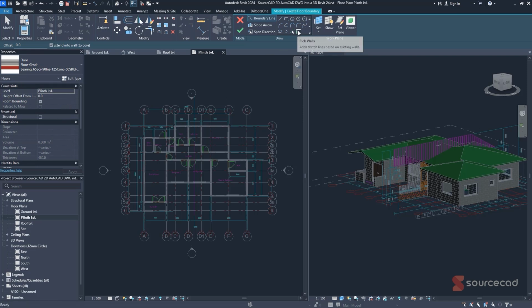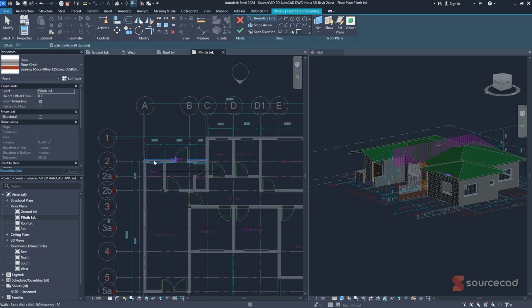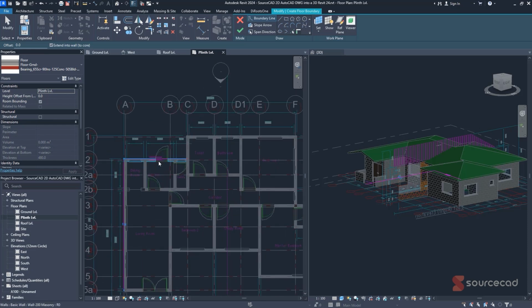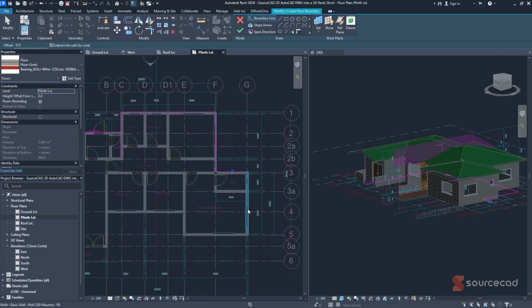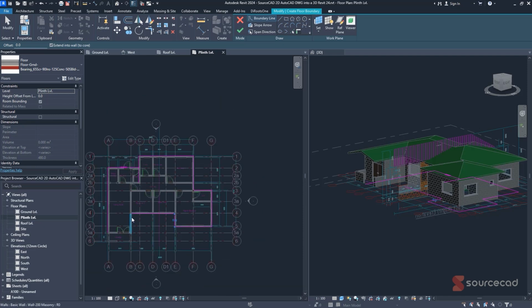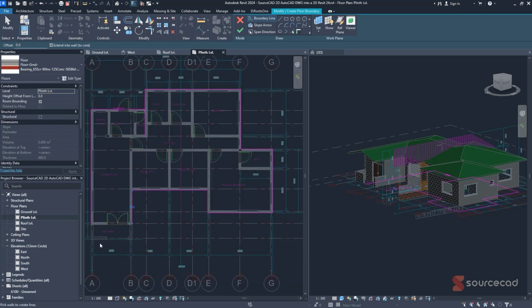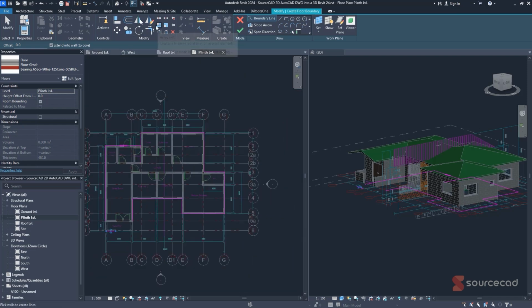So I'll pick on walls again, this option here. So I'll select this wall, that wall. So this is basically the span direction of the reinforcement of the steel. In the event that we are doing the steel reinforcement, maybe using a BRC mesh for this structure. So just like that, we'll come back and trim our corners just as we did with the roof. So go back here, trim our corners like that, make it just well tight and fine inside here,